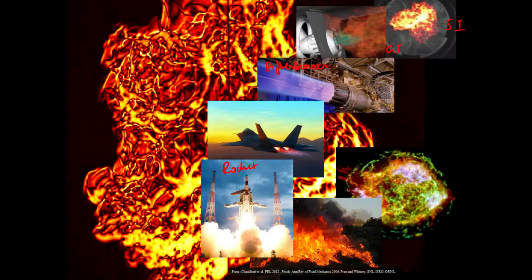The reason is that all these aero engines work at high pressure. That comes from thermodynamics: you must extract work only after you have input heat at high pressure. At high pressure your density is high, your Reynolds number is high, and as a result your flow is invariably turbulent, and you can only have turbulent combustion in these aero engines.